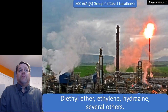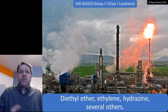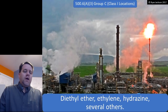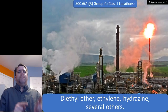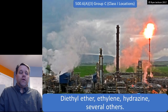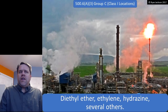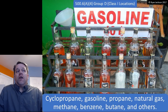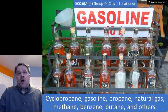Group C is much more common. Diethyl ether, ethylene, hydrazine, and several others, again, most of which I can't pronounce. Group C is much more common than Group B. Normally with hazardous locations equipment, it's going to be rated for Group B, C, and D, or it'll be rated for Groups C and D. So C and D are definitely the most common, Group D being the most common. Cyclopropane, gasoline, propane, natural gas, methane, benzene, butane, and lots of others. So Group D is your most common.